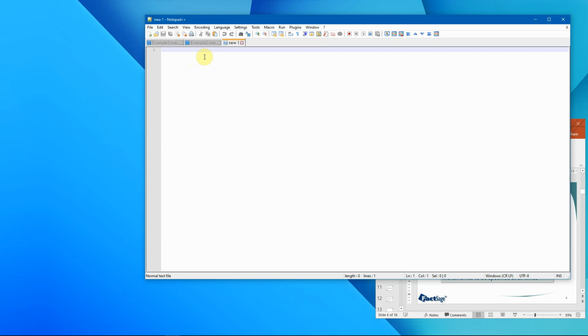It means that it will look for files and save files in that folder, which is typically C:\FactSage or C:\FactSage WS, even though you set the myfiles directory in the equilib module to a different folder. It will still look in the FactSage installation folder. So we need to indicate the full path to our files in the macro file when they are not stored in the FactSage installation folder.